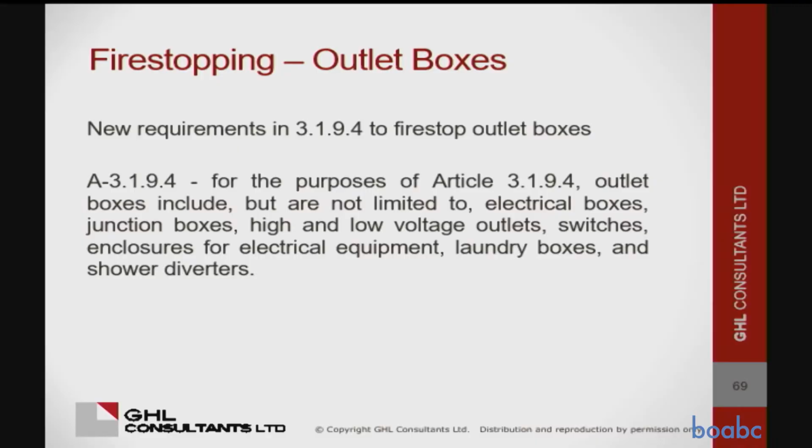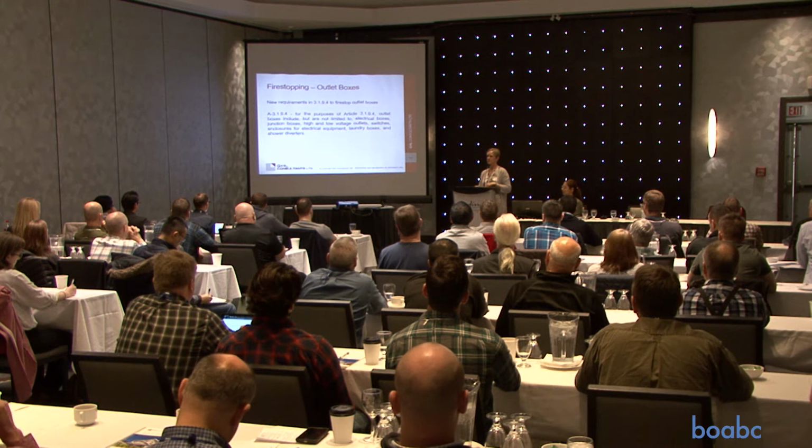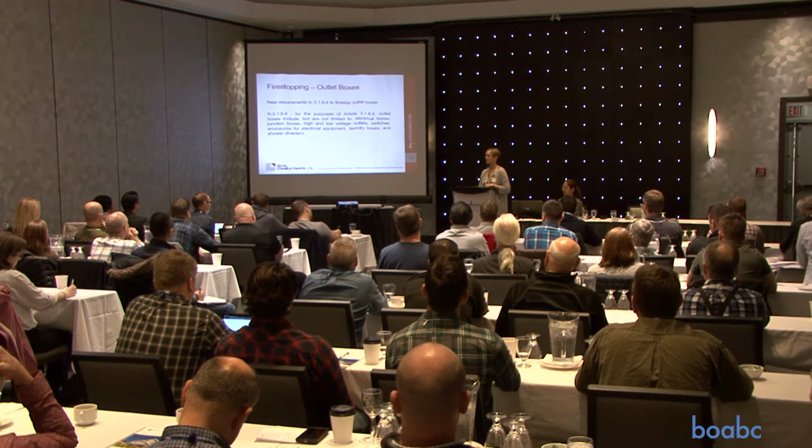Oh gosh, the outlet boxes. Anybody read the section on outlet boxes and fire stopping in the 2018? There's a couple of interesting things in there. There's a mistake, for one thing. It says you can waive the outlet box when it's tightly fitted. But it means you can waive the fire stop.